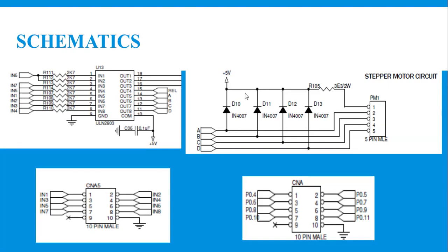Now coming to the schematics pertaining to the lab. Again, a stepper motor is a high load device. Your microcontroller alone cannot drive this. Thereby a motor driver is required. So we are now using a stepper motor driver ULN2803. The function of this is explained in the earlier video. Here the permanent coils of the stepper motor are A, B, C and D, and these A, B, C, D are in turn connected to the A, B, C, D terminals of ULN2803.